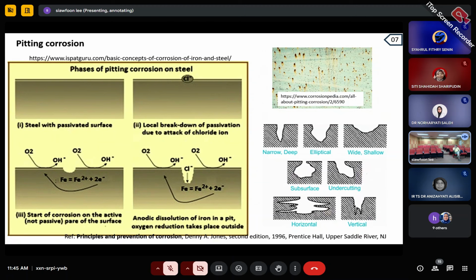For example, I have one study in the laboratory requested by a company. For a building with concrete and rebar inside, it will take 100 years to collapse. Of course, in the laboratory, we cannot wait that long. We are not going to live that long to obtain that knowledge. So people apply accelerated corrosion. The result that you get will be slightly different, but you apply it because you want to shorten the time and see the result.